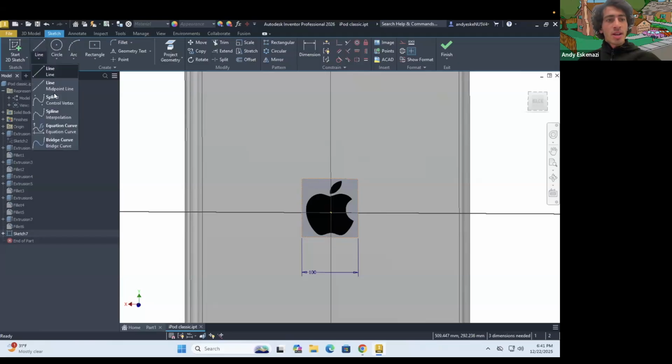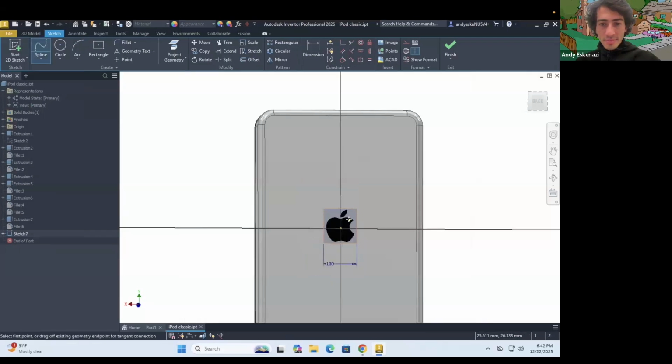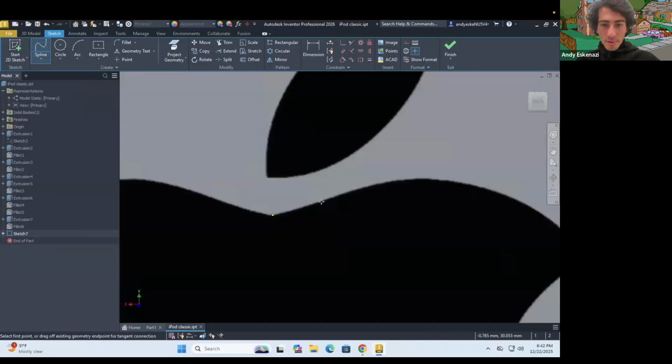Again, this is something that we're going to see in a lot greater detail in session 2. But I like getting a little bit ahead of myself and explaining these things early. It makes this thing look a lot prettier. If I click here in spline, I can say go, all right, I go to that point. And it's essentially going to start drawing a curve defined by the points that I place. Now, point of caution, in the interest of time, I'm not going to place so many points. However, you should place more, because that's going to influence the quality of your curve.